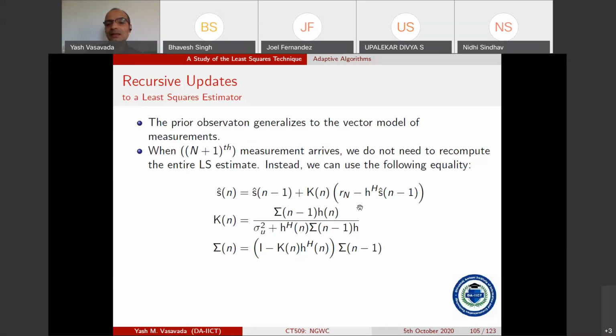And then in the real time, in the online mode, I just need to do this operation, the first equation, which is very, very simple. So I can pretty much trade the computational time complexity with the memory complexity or the space complexity. I will have to store all these k and sigma values, but then the number of fixed point or floating point operations per second, I don't have to worry too much about that, because that has become much simpler. The same solution I can get by doing the least squares, but if I have to keep on doing that matrix inverse every time I get a new data point, you can imagine that there will be a lot of flops, floating point operations per second, that may become unwieldy, especially as capital N becomes large.